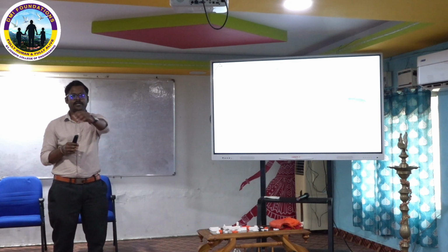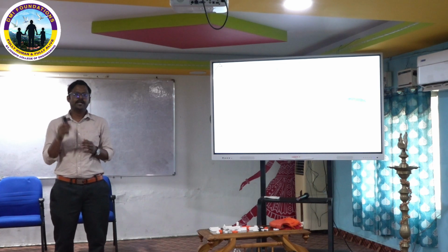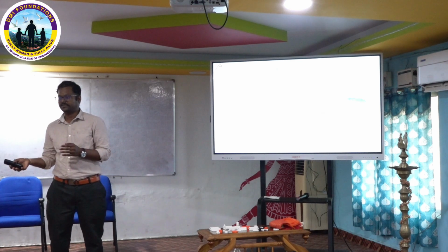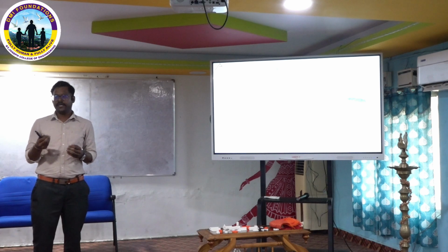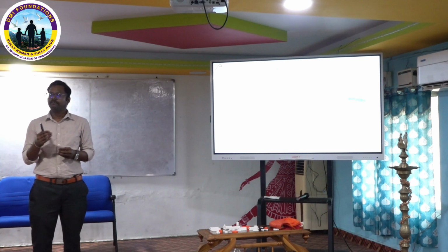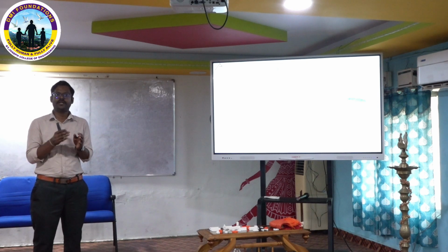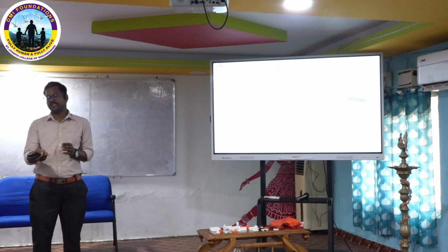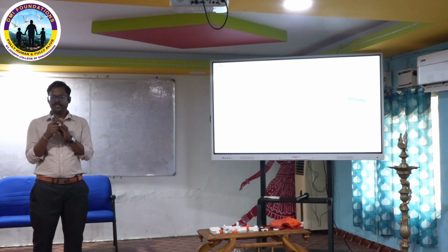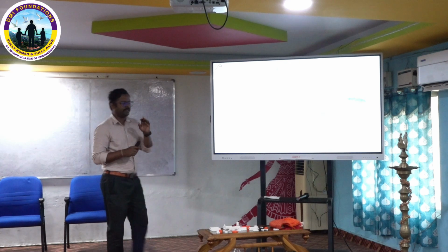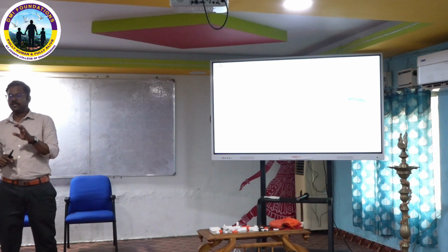How can I assign them? Especially for powder-based additive manufacturing, we get an anisotropic product. That means in the X, Y, Z directions we get different kinds of properties compared to conventional processes. With conventional processes like casting or forging, we can get like 90 to 95% isotropic properties. But in additive manufacturing, mainly we can get only anisotropic properties. So in the initial stage of research, we need to fabricate tensile coupons, test them, and from that test come up with the Young's modulus, density value, and other things. Then we give that as the material property to our design. We can't directly take the available library material properties. It will not give the exact result.